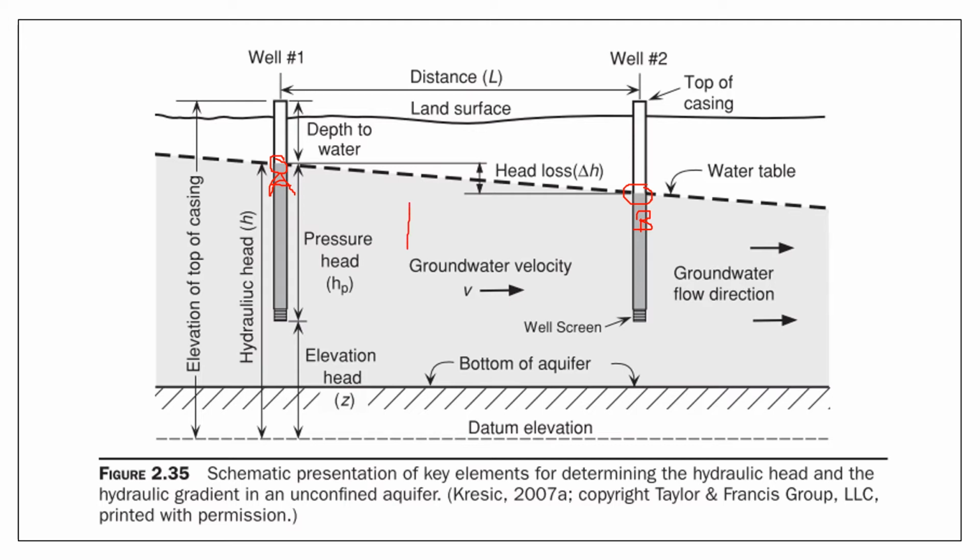First, of course, is K, or the hydraulic conductivity of this aquifer. We can get that number from a variety of tests, including well tests, or in situ field testing of the aquifer, which we will be discussing later, and also laboratory testing, which involves testing samples of your aquifer outside the field.